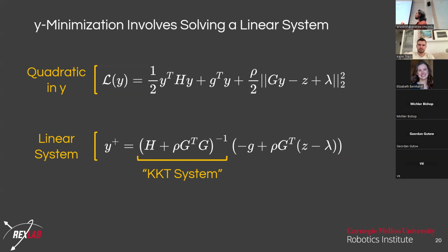But I don't know if you always have to, depending on where your initial guess is, where your solution is, and the subspace you're working in. For example, when we construct MPC problems, sometimes we'll let Q be positive semi-definite, but we'll have R be positive definite, and the constraints tie the two things together, so you don't need H to be strictly positive definite because the constraints will add that and make this whole thing positive definite.